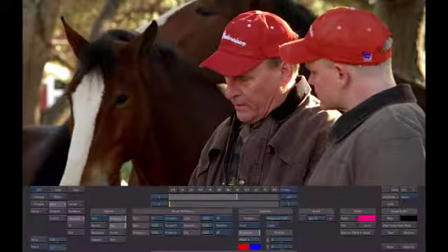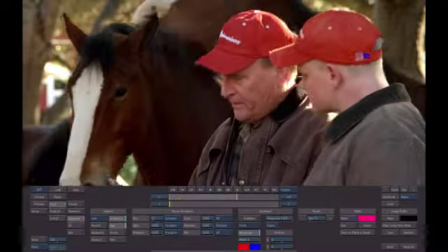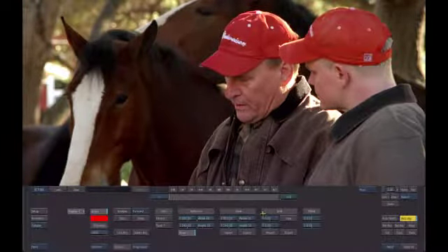And then what we can do is say, let's apply this to an entire clip. I don't want to do this on 1 frame or 2 frames or whatever. I'm just going to step in and do it, but of course the hat moves, so this is where we want to start accessing some other tools. So we'll go ahead and access the stabilizer.